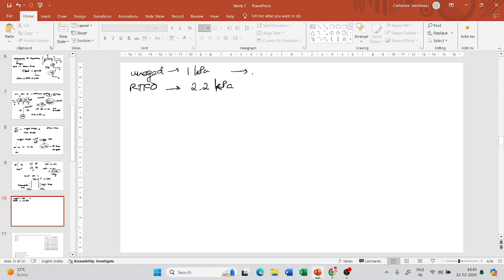Now you know how to determine the PG grade of bitumen, right? Let us say my PG grade itself is changing, okay. Let us say my PG grade is 64, and when I did RTFO, my PG grade was found to be 70. Okay, it can happen. It can either be more or less. Anything can happen. So now you have 2 PG grades for the same bitumen at 2 aging conditions, but you have to give only one high temperature PG grade of bitumen. So how will you do? As I said, you should always be on the safer side.